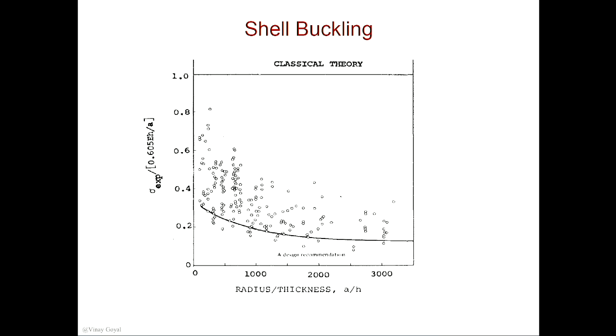And on top of that, Abaqus is looking at a linear perturbation about the perfect shape. In real life, you may have a dent in a structure or some amount of imperfection that you may not be able to see very clearly. Now the perturbation is not about the perfect shape, it's about that new shape, and that new shape will lead to unstable behavior. So for example, in the ruler case, these are fairly stable. Sorry for the ruler, it's probably dying little by little. Although I'm putting it here, and it looks fairly flat, so it's pretty good material. But we can see in this case, it's fairly stable as I load it up. In a shell, a small amount of imperfection is going to result in an unstable buckling behavior, while in this case, it's a more stable loading environment, right?